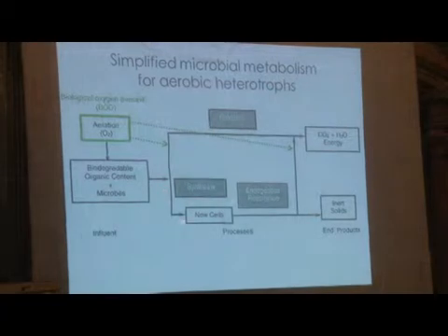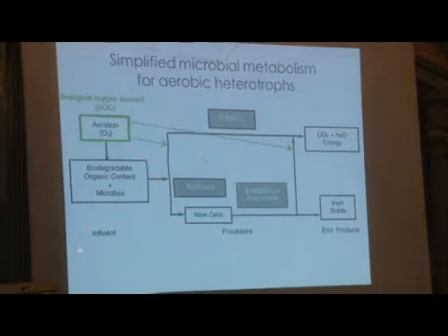It's a chemical compound, allyl thiourea. We can add it in a concentration of 20, 30, 50 milligram per liter, and then the nitrification will stop. At that moment, oxygen will only be consumed for the oxidation of carbon. Part will go to new cells. So this is assimilation. We call it synthesis of cells. This does not consume oxygen.